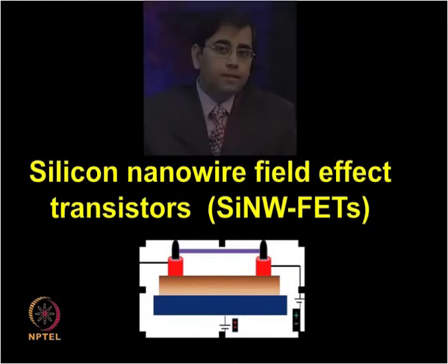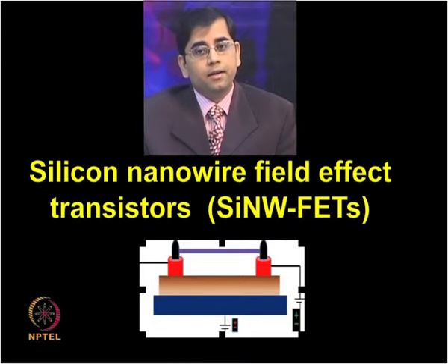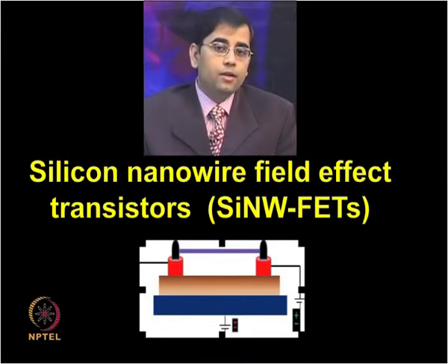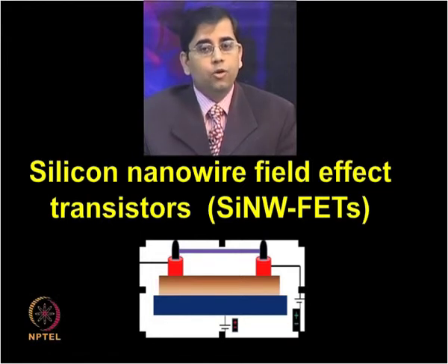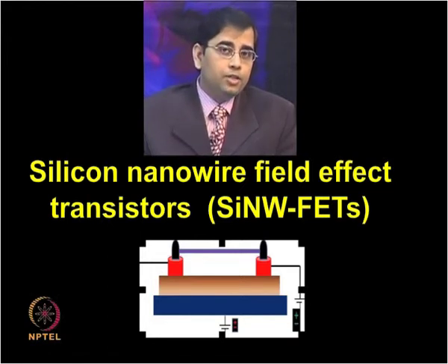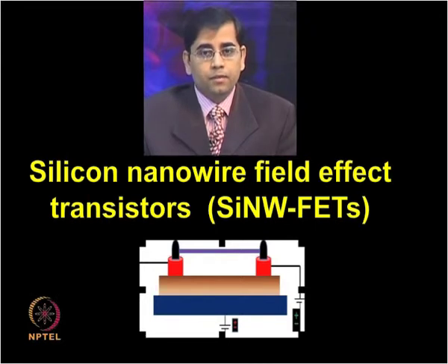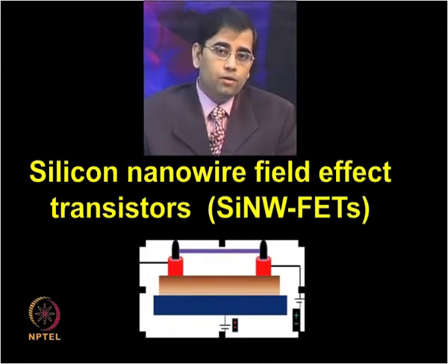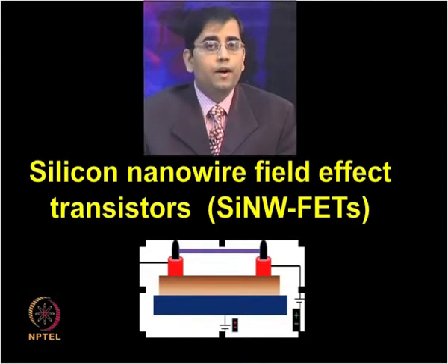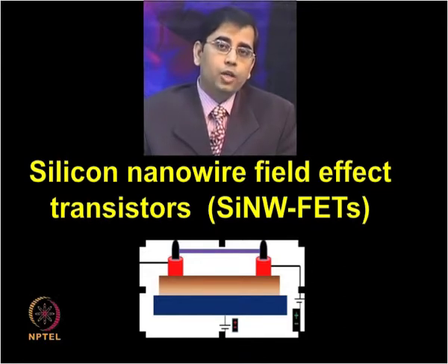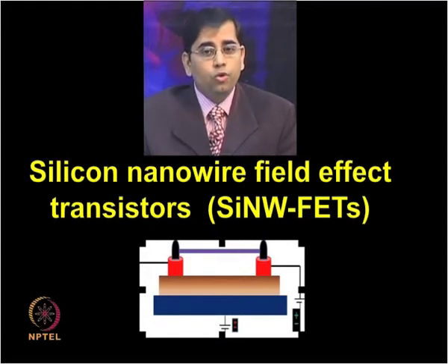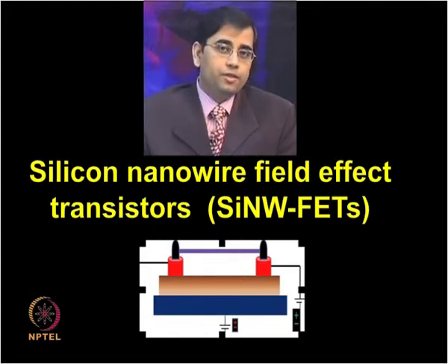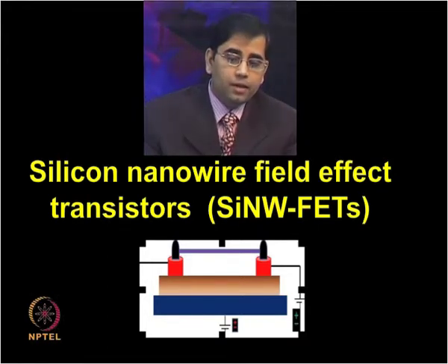The silicon nanowires, which are always semiconducting, are potential building blocks to fabricate the functional nanosensors that overcome some of these limitations which we just discussed. In addition, they allow sensitivity to be fine tuned as per the requirement by controlling the type and amount of dopant in the semiconductors.